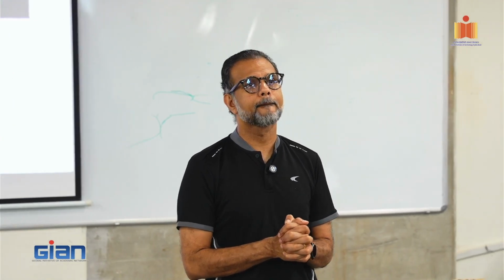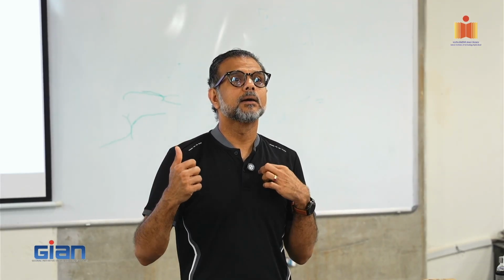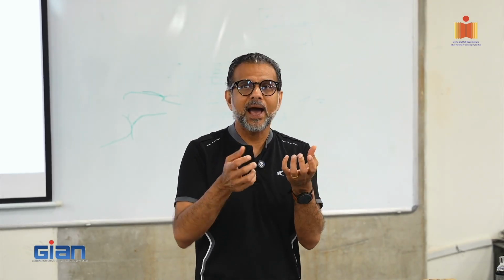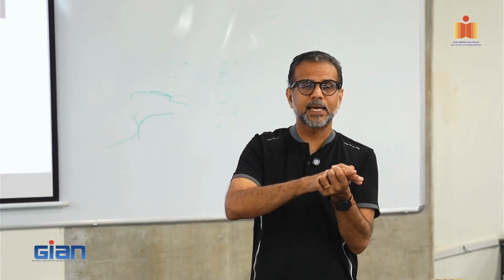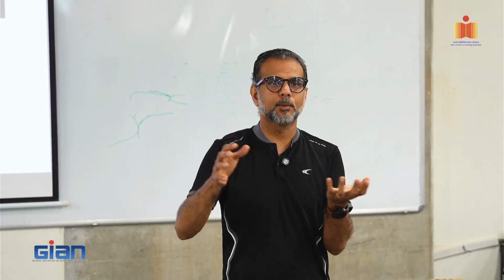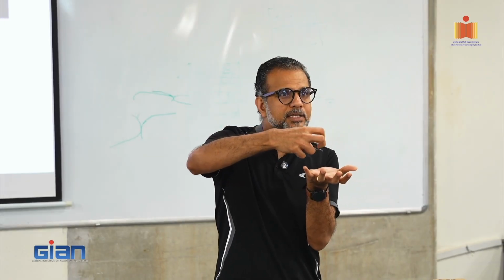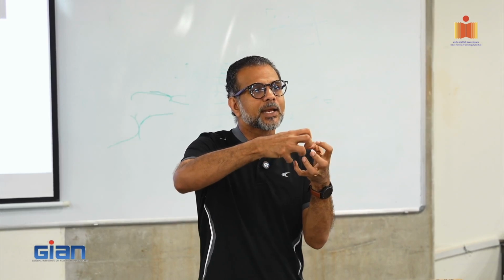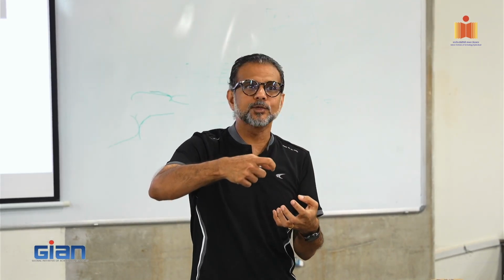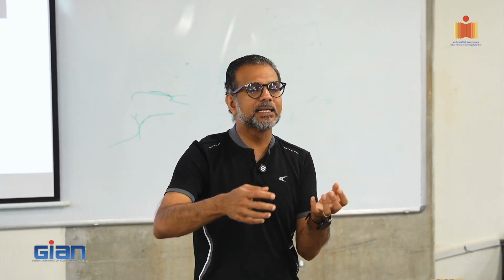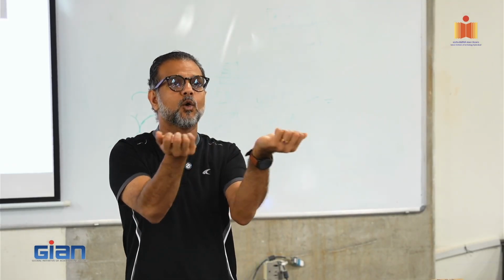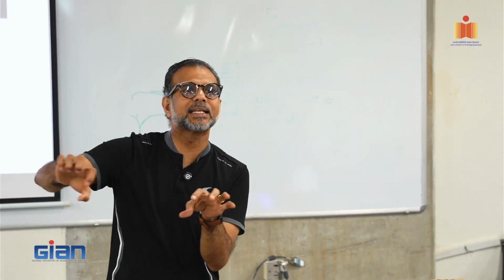Yes. Voids, I showed you, right? Void sizes. Some of the recent work in 3D tomography has shown that because you're extruding, the voids normally have a tendency to be spherical. Depending on the extrusion velocity and the conditions, some of your voids become spheroidal. Some get elongated, ovalish voids along the direction of printing.